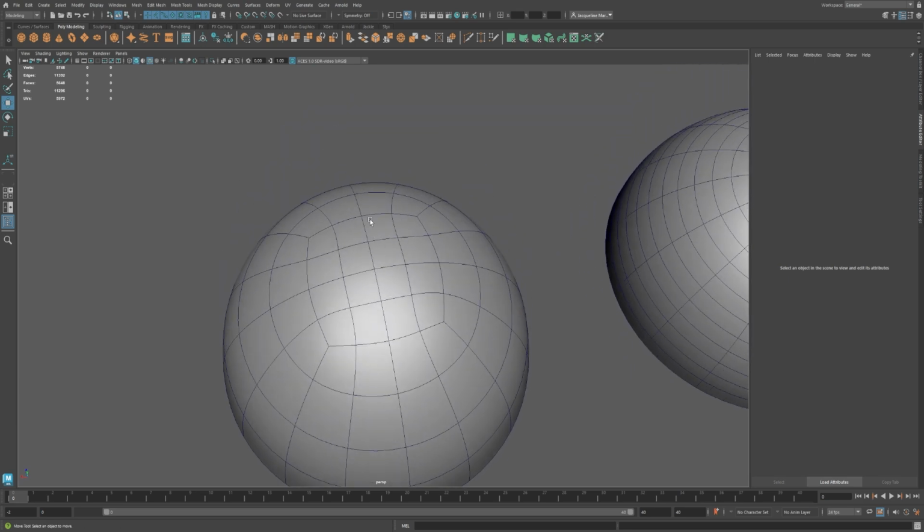Now the problem with this is that this tends to cause points that may pull here. Notice the similarity of the shape. This is very similar to that triangular shape that we were trying to avoid earlier when we take a triangle and we add its subdivisions. So the same effect can happen here. It's not going to pull the same way because we've created these edges, so this edge isn't going to pull out in the same manner that it did before. But because we don't have an even distribution and the surface area of each of these is different, this is going to tug a little bit at this point.